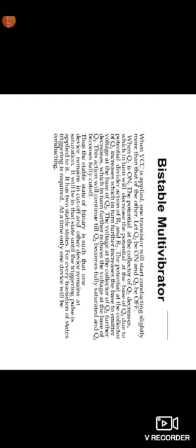Here the VC2 voltage is connected to the transistor Q1. Here the VC1 voltage is connected to the transistor Q2. The voltage at the collector of Q2 further decreases, which in turn further reduces the voltage at the base of Q1, so that the base voltage suddenly reduces further, so that this action will continue till Q2 becomes fully saturated and Q1 becomes fully cut off.